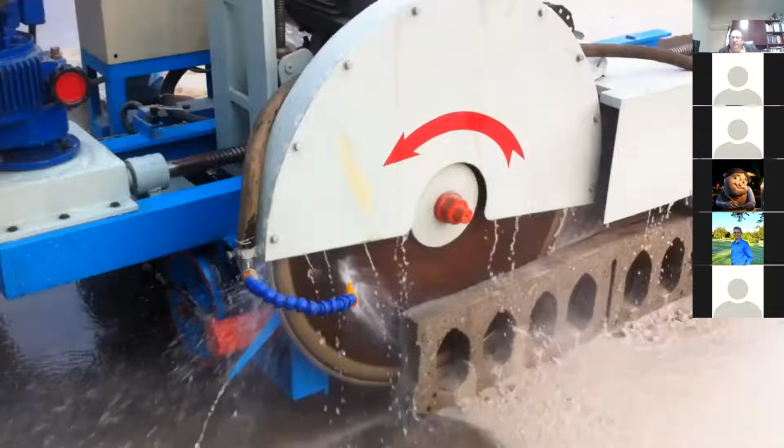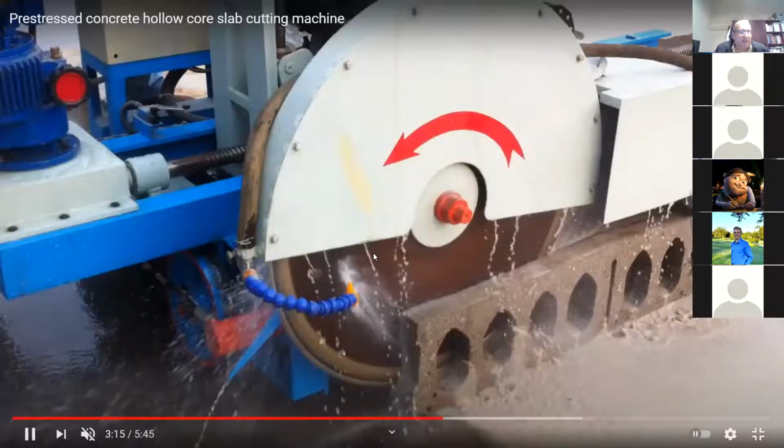In bridges, you go continuous. In elevated slabs, like the project I told you about in San Francisco, that was a continuous slab. It was post-tension, so we were able to go top and bottom. Whenever I need it in tension, I'm going to put it there, and I can also add a little bit of reinforcing. But usually it's going to be simply supported, stuff like this.